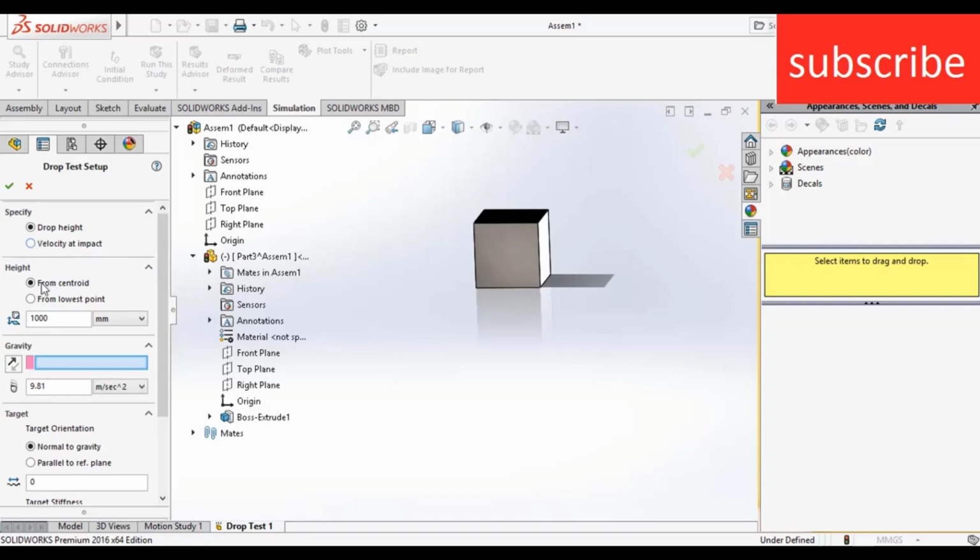Here there are two things. I will tell you both of them. So first let's talk about drop height. Basically drop height means that you are throwing your part from a certain height. You will tell what is the height, and here you see two things, from centroid or from lowest point. From centroid means the center of gravity, and from lowest point means the lower point. So I'm selecting lowest point and selecting the direction of gravity downwards.